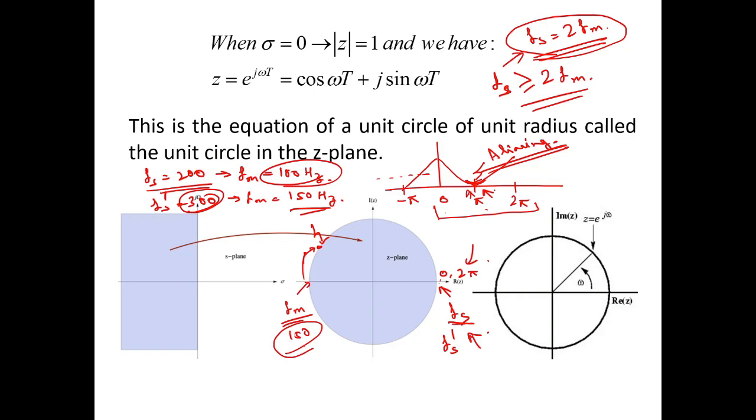You have to make sure that you do not have aliasing, and also keep in mind that you do not want to oversample beyond a certain limit, such that there is no cramping of the signal, and you can design the filters in a more comfortable manner. Okay, so this is it. And also your storage requirement will be quite less.